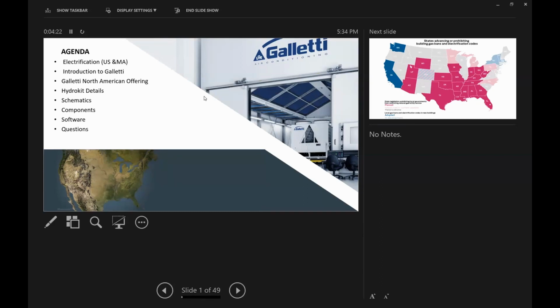there's a lot of solutions out there with the electrification, decarbonization that as we're removing boilers and all these different items, there are substitutes where we'll continue to be making pump selections, heat exchanger selections. So a lot of the stuff in this class, I don't see at any point it becoming obsolete. Pumps, heat exchangers, and just fluid water in general. Water is an excellent heat transfer medium, and I don't really see any long-term solution for replacing it.